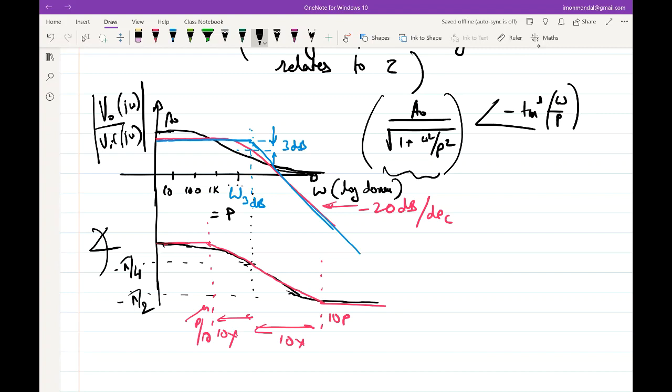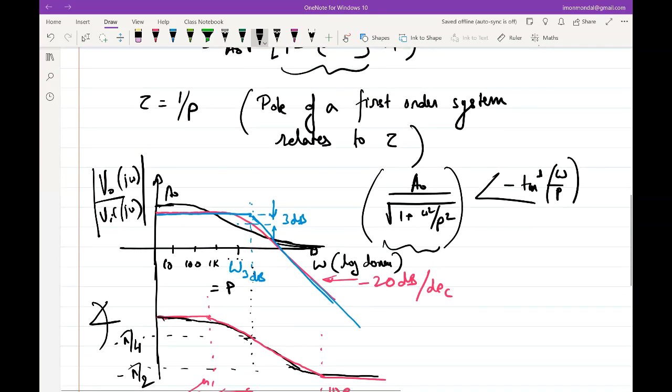analyze. And also we saw that the time domain response of a first order system corresponds to, what? It corresponds to a typical RC charging, right? And we are comfortable with that. So since we are comfortable with that, we'll go back to our comfort zone. So every time we write something in terms of a first order system, it need not be in the context of an RC circuit. It can be anything. At the back of your mind, you should think that the way this system will settle will be similar to how an RC circuit settles.